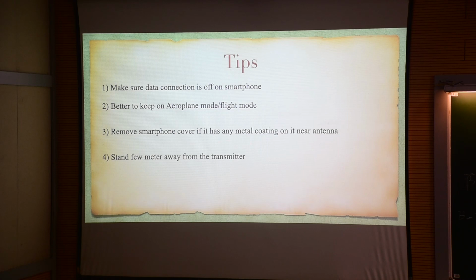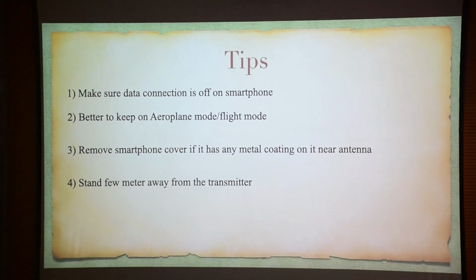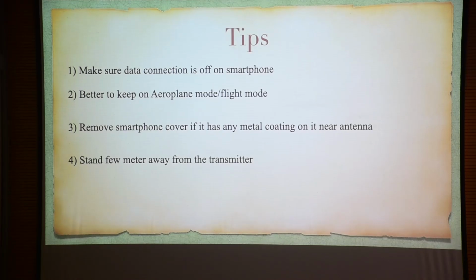Okay, so remove the smartphone cover if you have one, and sometimes these covers are made of metal, and we should avoid that because those are good reflectors as well as absorbers. We also need to take care that we should not be very close to the setup because we ourselves might also be reflecting those signals. So we should be away from this setup, whether on the transmitter side or the receiver side. And whenever we are taking observations, we should not move between the setups or across the setups.